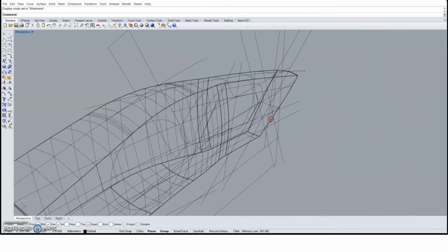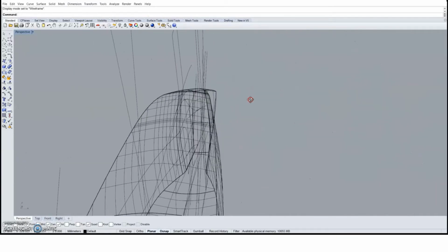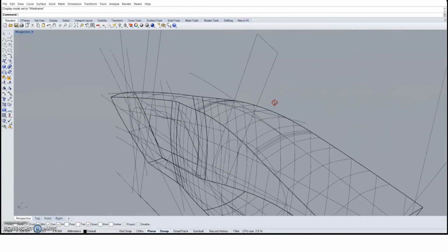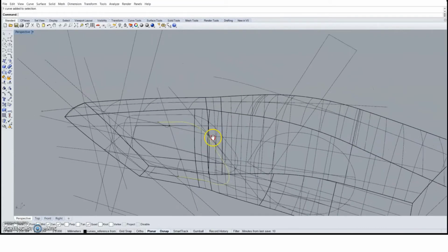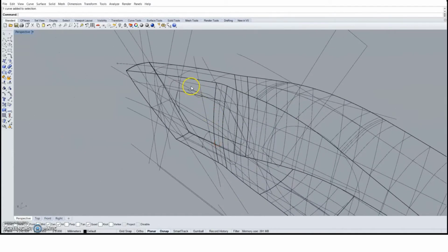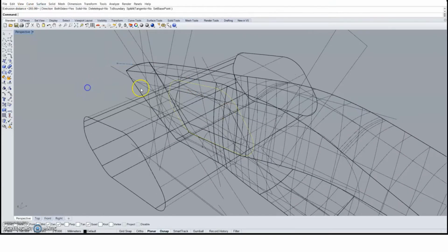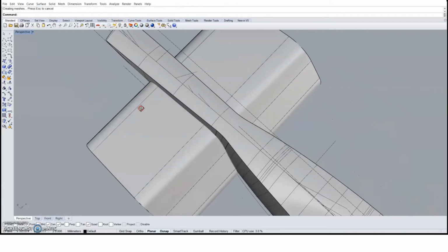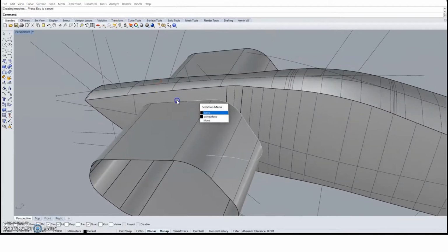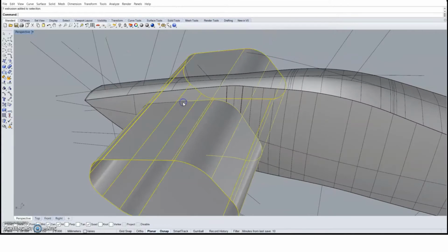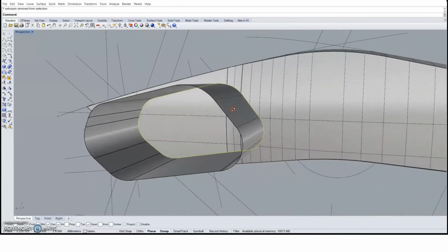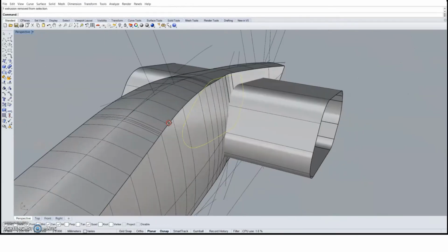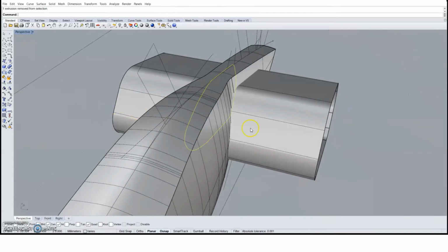And we're going to continue to cut an opening for the handle using the curves that we defined earlier as well, using the sketch as a reference. And we're going to extrude the surface here and use that to cut it. Basically, we're going to cut a hole on the two side surfaces. But first, we're also going to create curves so that we can use the curves as references to build the rest of the internal surfaces, which you will see later.